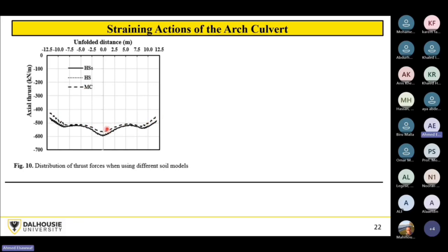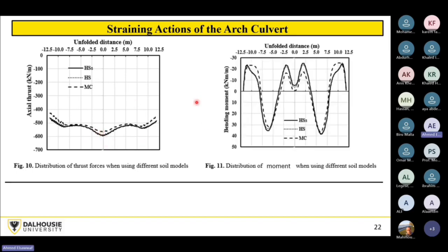Underestimation means that you will get lower buckling stresses and lower axial compressive stresses, and this can deceive you and lead to a wrong design if you take a lower section in this design.